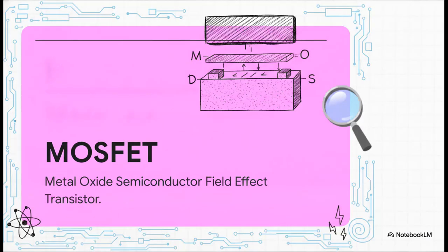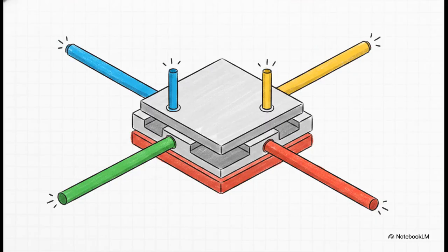It stands for Metal Oxide Semiconductor Field Effect Transistor. Let's quickly break that acronym down directly from its physical materials. The top conductive plate, the metal, is actually often made of a really good conductor called polysilicon today. The oxide is the incredibly thin silicon dioxide insulator sitting right below it, and the semiconductor is that P-type substrate we built our channel on. Because we had to stretch everything up to the top, the modern MOSFET ends up having 4 distinct terminals extending out. We have the gate, which is that top plate. We have the source and the drain, which are made of heavily doped N-type material so we can make solid wire connections to the top of the wafer. And finally, we have a connection to the substrate, or body, at the bottom.